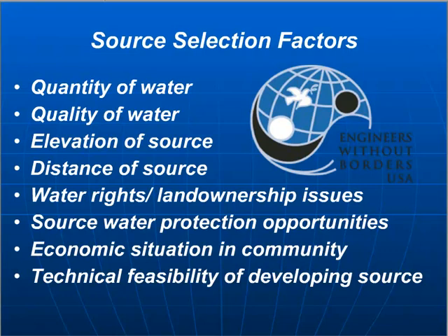So are they at least 10 meters above where you need that distribution point to be? Distance is another thing. Maybe there is a gravity-fed source, but it's over 10 kilometers away, and so it's not feasible for something that large, or maybe for your chapter that is something feasible. I don't want to set any hard limits for how far you should look, but sometimes just the distance alone is too much, just considering the capital cost and the ability for the community to go and visit that source area and make sure it's clean.